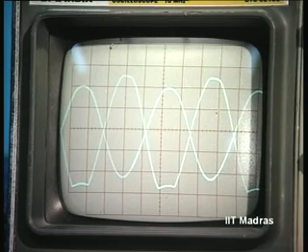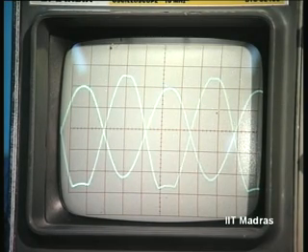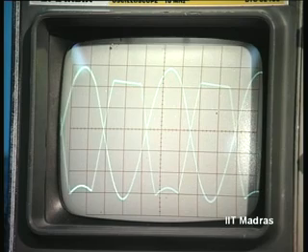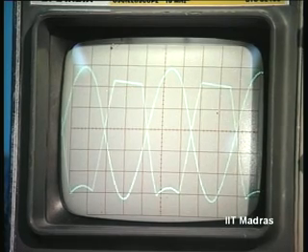At the cutoff, of course, the supply voltage is going to limit. Now if you increase the signal further, let us use brute force. You see the top is chopping off, very clearly indicating that it is going up to the supply voltage. In the bottom you have the transistor deep in saturation. So this illustrates very clearly the signal limitation.